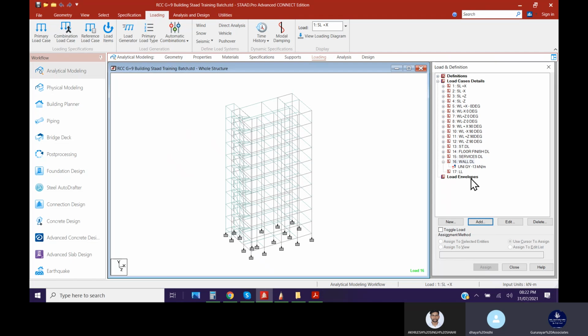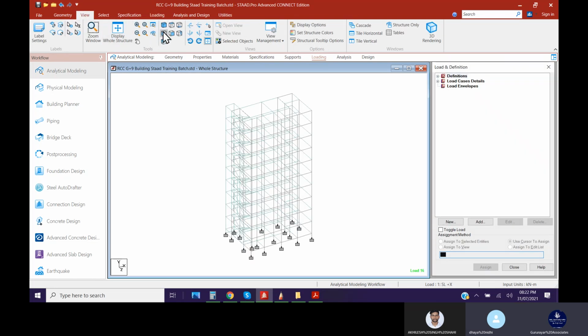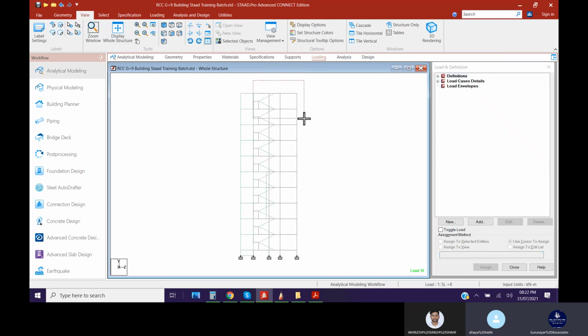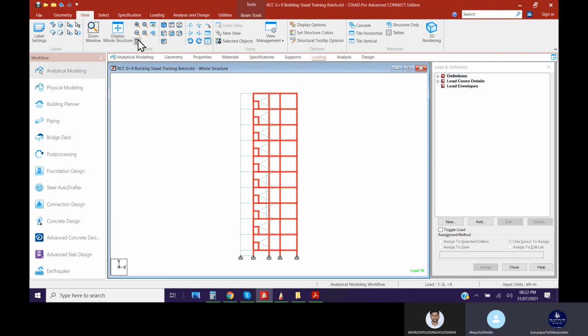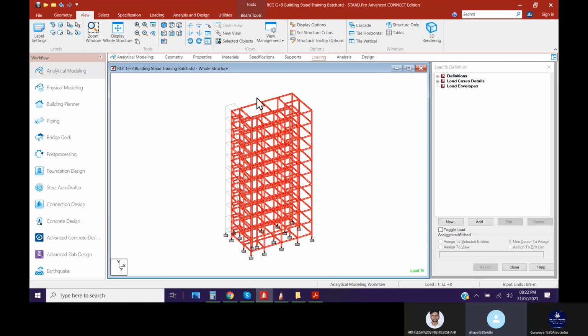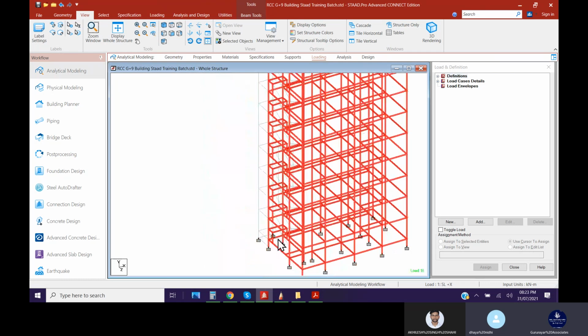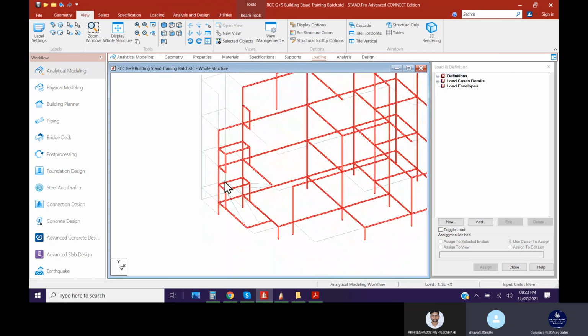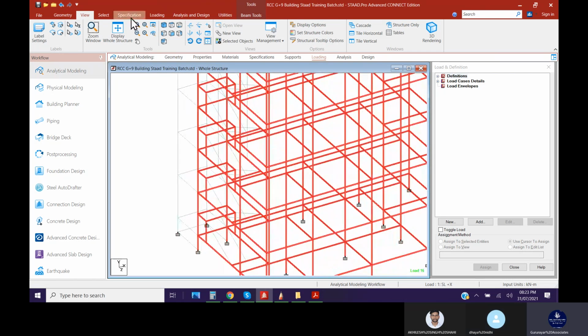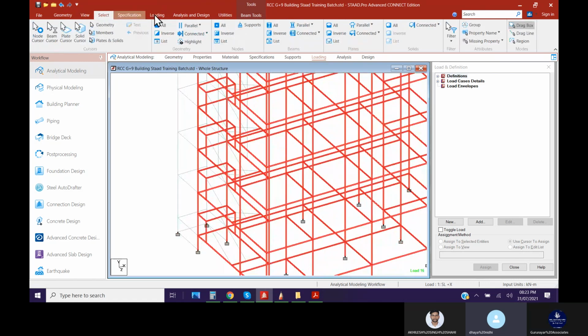The load is added. So for which beams will you assign this one? You have to select first all these beams. But for certain beams, walls are not required. So you have to deselect wherever that is not required. Select first, then deselect. Columns are also not required.